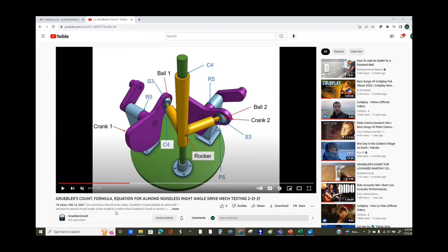So I said, well, let's fix it with Gruebler's. So what I did is I applied Gruebler's. I made this spherical, and this is spherical. And what happens if you mount this a little bit off? You see that it's off, right? But watch, it'll still run. It just wobbles a little bit, but the system lines itself up because of Gruebler's.